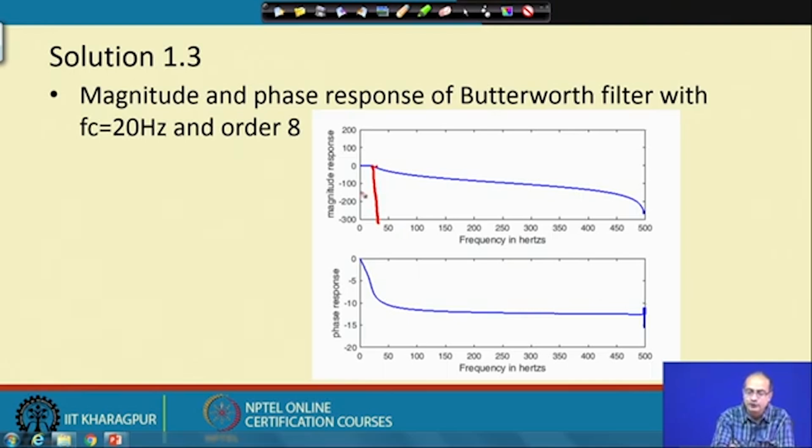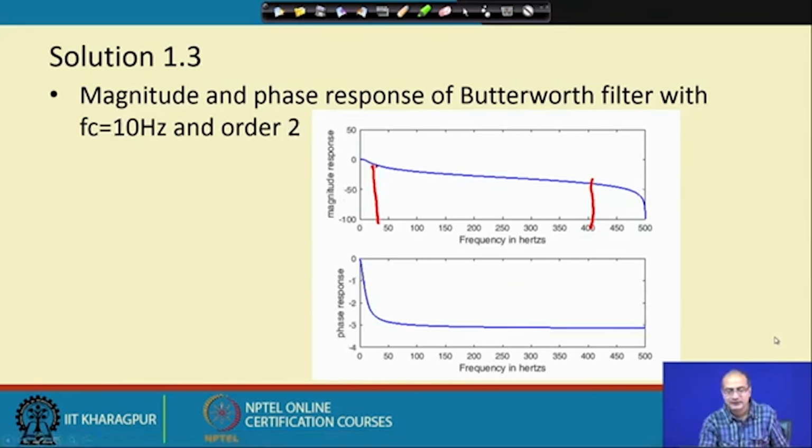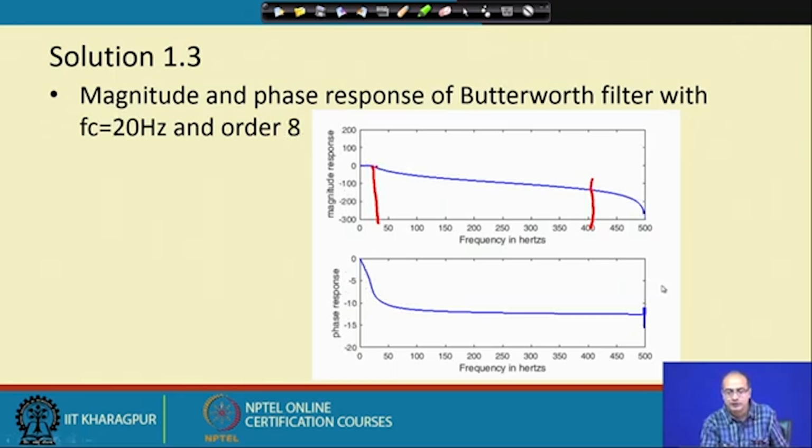After that there is a decrease, and the decrease is more pronounced. Okay. If we look at 400 hertz, what was the decrease? If we go to the previous case, we would be able to appreciate that. It was actually less than 50, the decrease in the previous case when the model order was 2. Now, though the cutoff frequency has moved towards the right, the decrease is much more pronounced, and I think it is about -100 here. Okay.